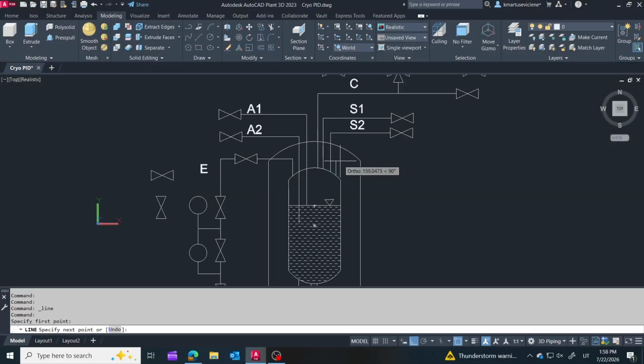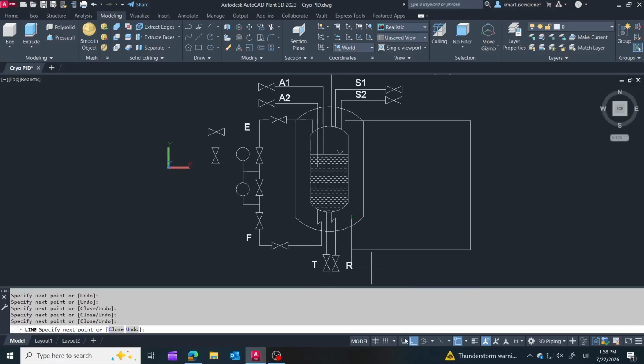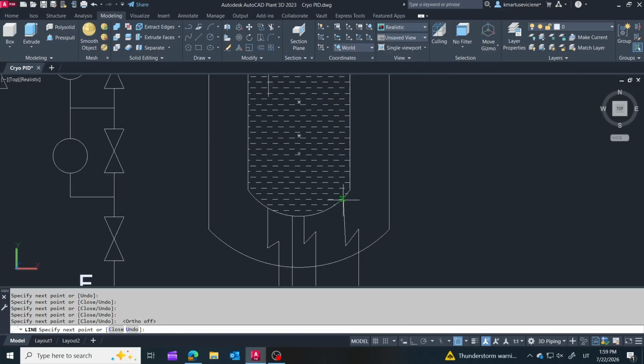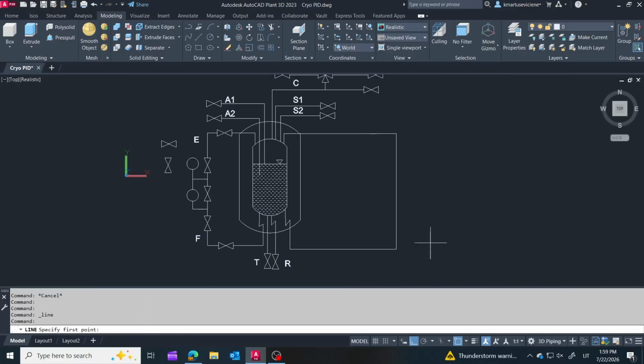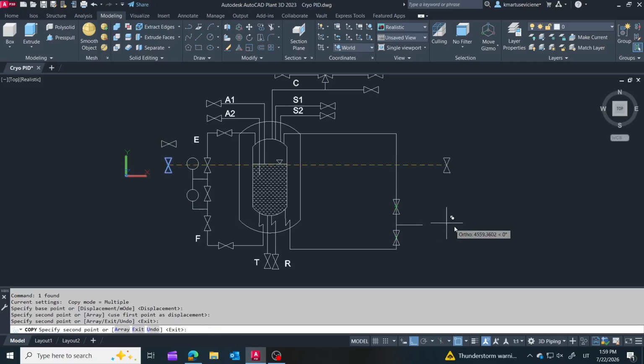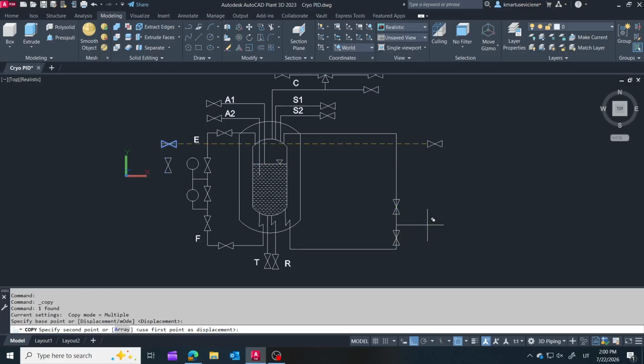This tank provides both a top fill and a bottom fill connection. During top filling, liquid nitrogen enters the vapor space above the liquid level. The extremely cold liquid cools the nitrogen gas inside the tank, causing part of it to condense back into liquid. This helps reduce pressure rise during filling. Bottom filling, on the other hand, introduces liquid directly into the liquid phase. It minimizes turbulence and is typically used for normal filling operations once the tank is already cold.